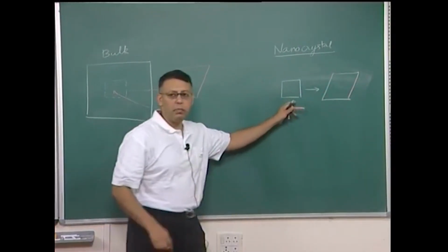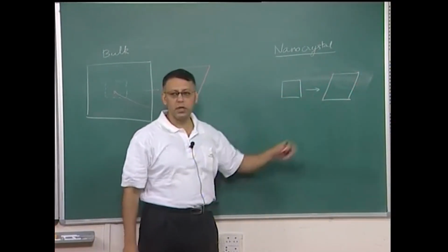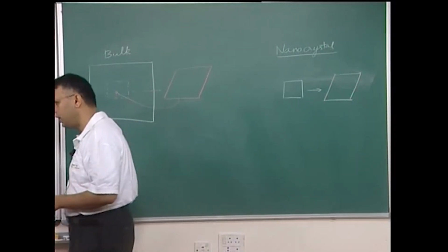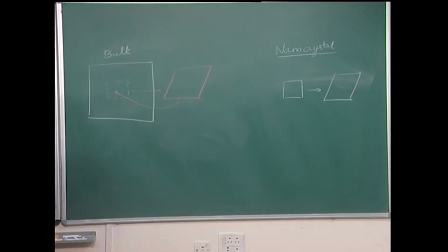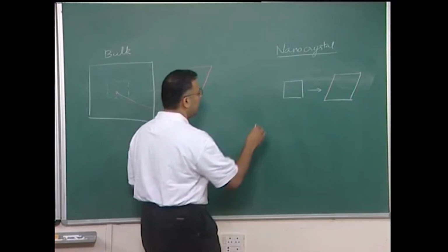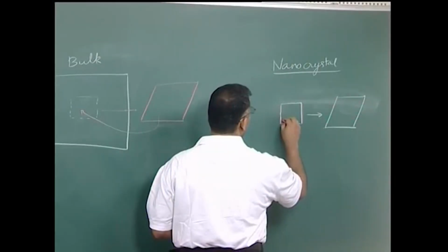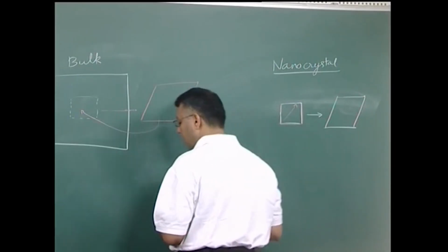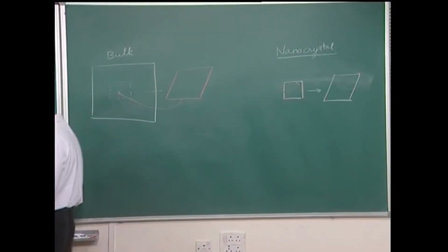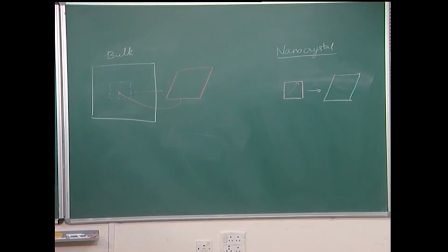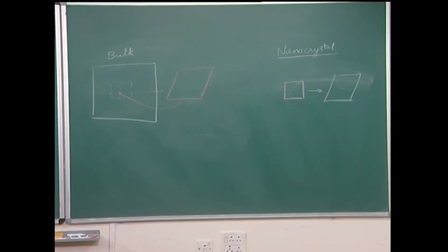there is no surrounding medium, therefore this transformation can proceed with lesser constraint. Additionally, we have already noted that there can be surface diffusion dominance, and the overall length scale for diffusion could be small. Therefore, even if it is a diffusional transformation or a diffusionless shear transformation, the overall expectation is that the strain energy term is going to be a small term, and many times we may like to ignore the strain energy term in the phase transformation.